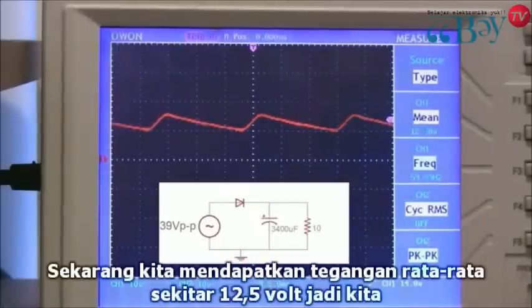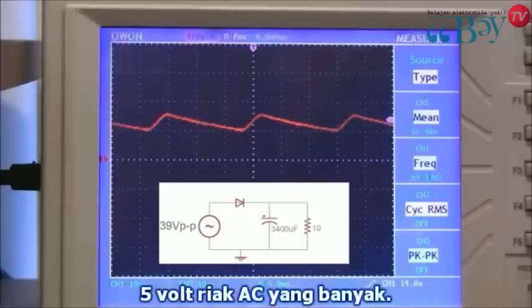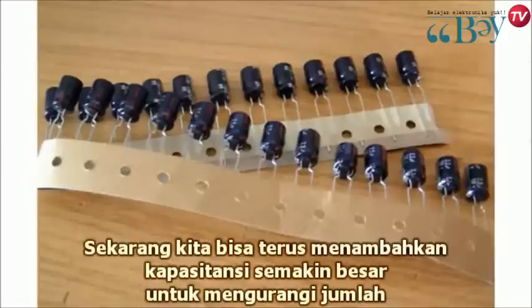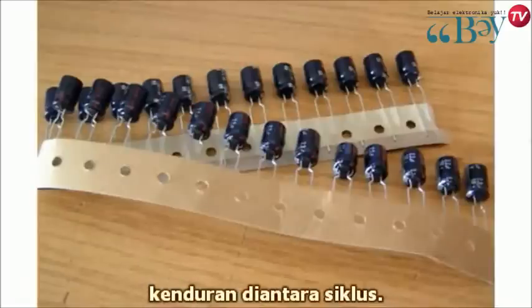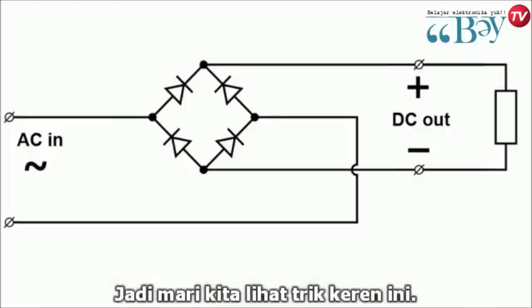Well, it's better. Now we're getting an average voltage of around 12.5 volts, so we're drawing an average of about 1.25 amps, but we've still got 5 volts of AC ripple, which is a lot. Now, we can keep adding capacitance all day long to reduce the amount of sagging between cycles, but for loads of several amps, it just becomes really impractical and expensive.